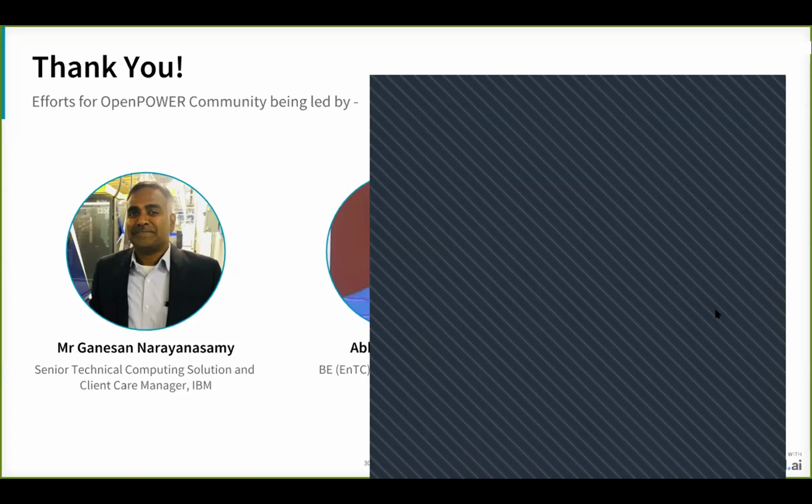RV32I or RV64I are the base ISAs which support only integer operations. How they have planned the ISA is with single letter extensions. The basic RV32I core has something like 50 instructions, but it won't have features like floating point operations or multiplication and division. To add that, you have the M extension, the F extension for floating point, the D extension for double precision floating point, and many others coming up, like vector for matrix operations. So I think Pulpino can support multiple extensions of RISC-V, not really two different ISAs.